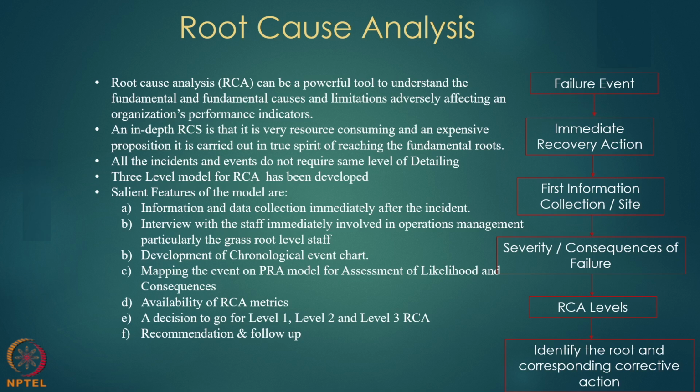So I talked about the levels. The major features of the RCA are, first, data collection. The data collection format has to be very good, and that requires interviews with the staff also, because sometimes very vital inputs are available when we interact with the staff who were there when the accident took place, or manning the areas. Then comes development of a chronological order, how things have evolved over a period of time. That mapping has to be done, and then we try to assess the likelihood and consequences, maybe qualitatively or quantitatively.